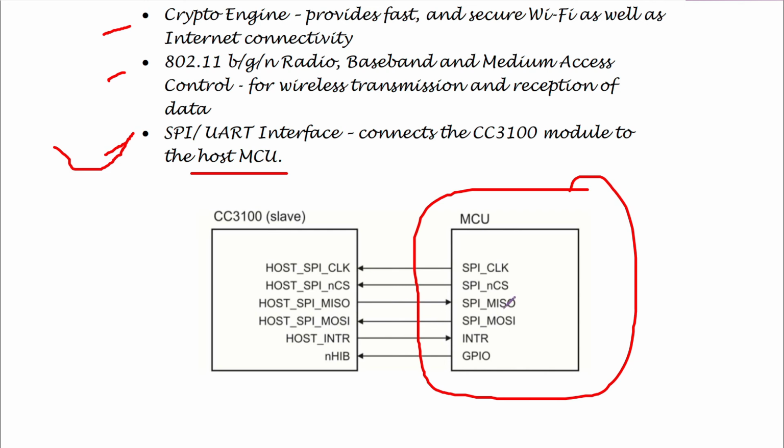Then there is a chip select. This chip select can be used or any other GPIO can be used, as we have seen in the unit 1 lectures as well. So here we are using the microcontroller, that is the master's chip select, to connect to the slave's chip select, so that this particular slave is being used using SPI communication. Then we have the other two pins, that is MISO and MOSI. So we can see the master in slave out is in this direction from the slave to the master, right? And then finally the master out, slave in, is from master to the slave.